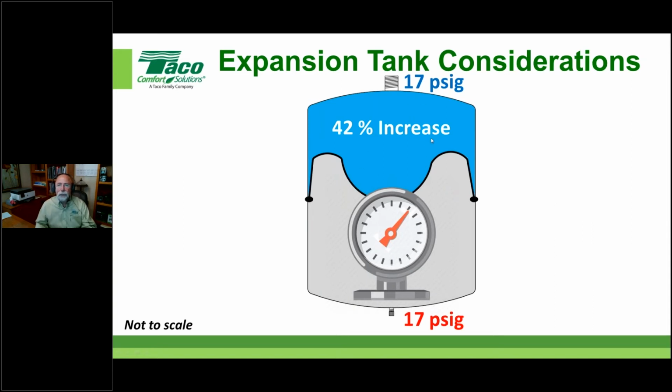And that's what's happening when you see your gauge change within the system. Yes, the fluid's expanding, it's coming in here, but we're getting an increase. We never get to see a gauge right here, nor would we ever want to. You don't really need to, other than a quick little press on your accu gauge that could tell you what it is. But again, when this is happening, when the system's running, is not the time to be playing with a Schrader valve. Okay, there's really only one time, and that's when the tank is completely disconnected from the system.